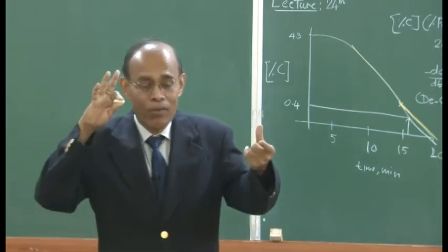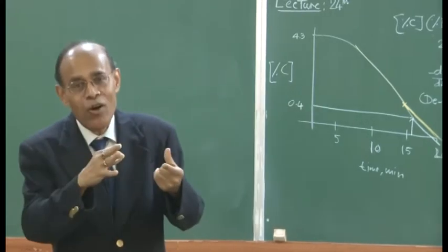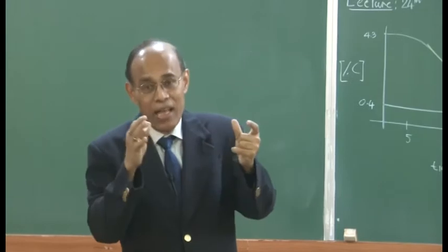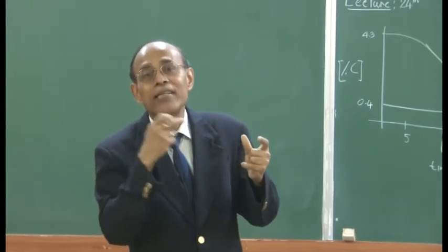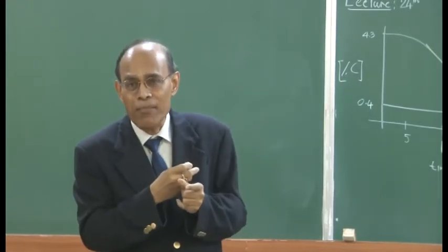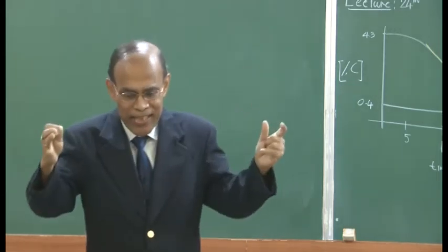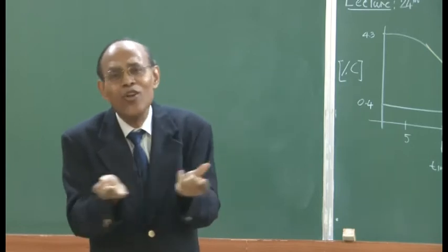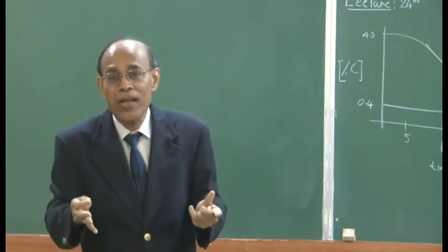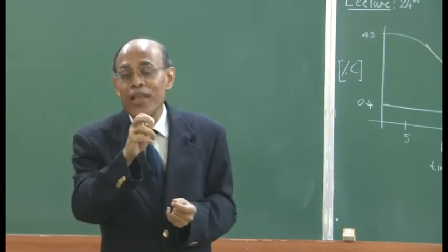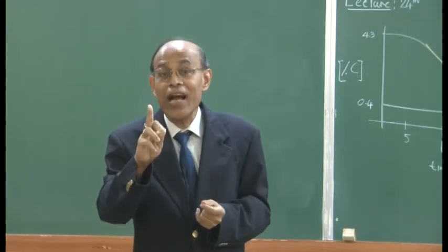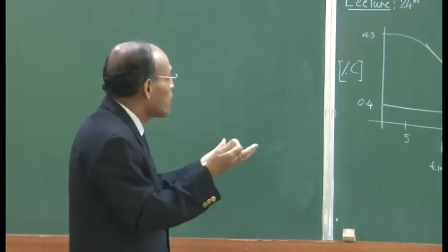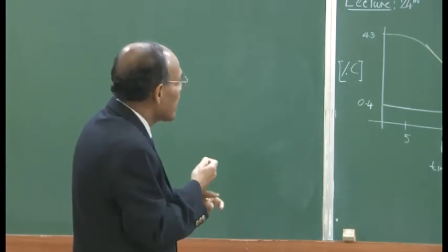So, what does it do? You are supplying oxygen, so the kinetics is getting affected. The mode of oxygen injection will affect the generation of convection currents in the system, because these combination blowing steel making reactors as well as the top blown oxygen steel making reactors, they all look the same, they have the same shape. What is the essential difference between them is the mode of gas injection, how you inject the gas, and the quantum of gas is also dictated, and more or less the blowing practice is identical.